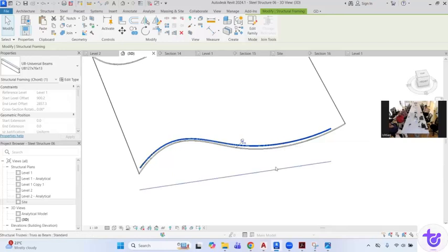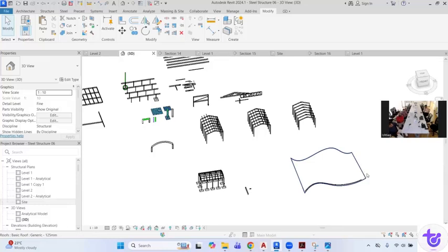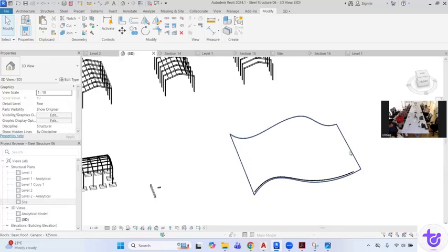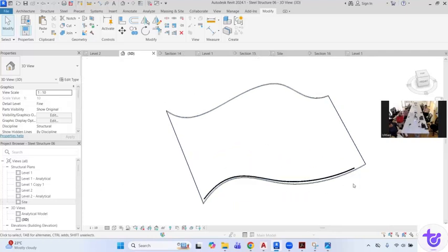One question. We are adding the roof as a curtain wall. We cannot manipulate the curtain wall profile. Will it also follow the roof? Yeah, actually it is following the roof. Whatever the category, it is following, because attach and detach option is only available for the floors and the roofs. So roof it can follow. If you have something else, then I think it may not follow.